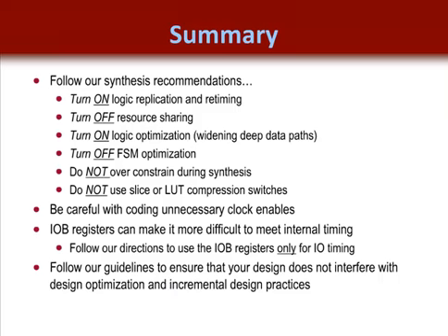So our solution to that was we want to tell you to override the default behavior of the tools, both your synthesis and the implementation tools, to use those IOB registers automatically, but instead only use them for I/O timing. And the best solution there was hopefully your synthesis tool using timing constraints to migrate registers into the IOBs.